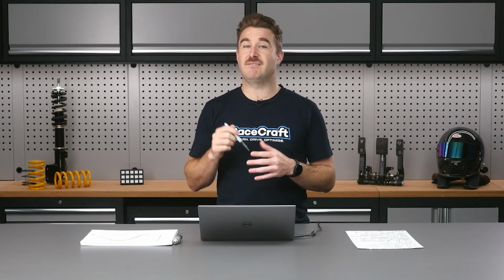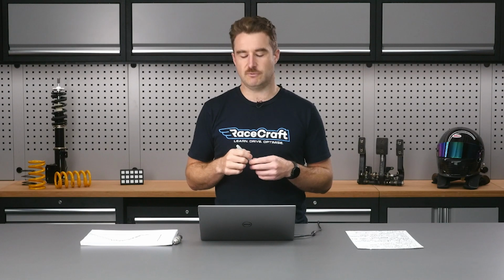What I would say is what we looked at towards the end of the lesson I did, where I was talking about using brake travel versus brake pressure. If you're tracking that as a metric throughout the race, as I said, the slope of that line, if it's something that's slowly changing over the race, let's say you've slowly got brake fluid boiling and you're introducing more air into the system, you know that the brake stiffness is going to be getting lower and lower, so the slope of that line is going to be getting lower and lower. If that's something you're tracking, you can either look at it manually or put some metrics on it and track it over time. But apart from that, if it's going to happen instantaneously, it's probably not going to be too useful for you.